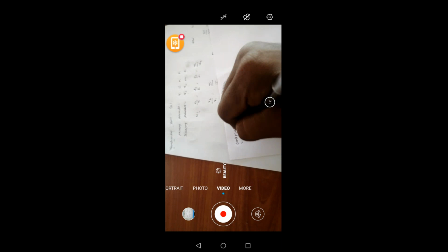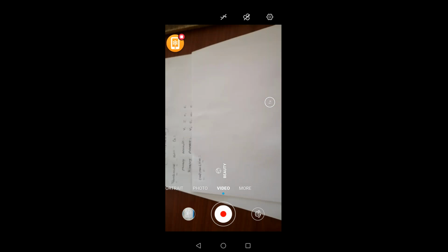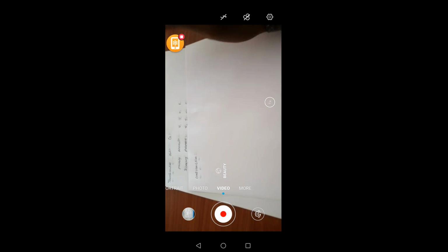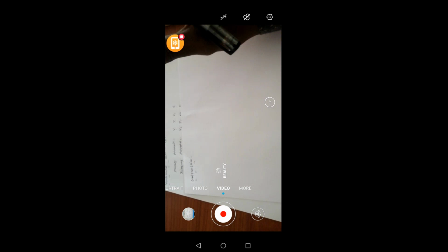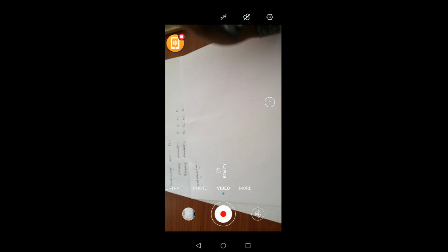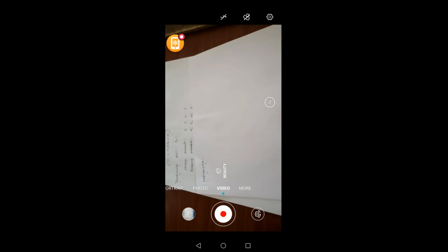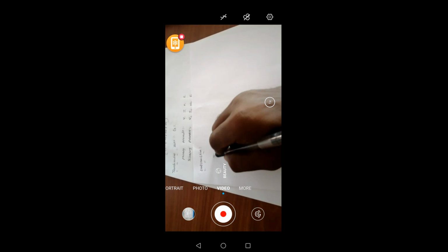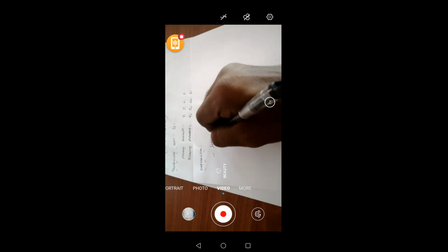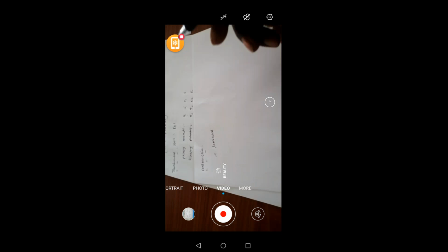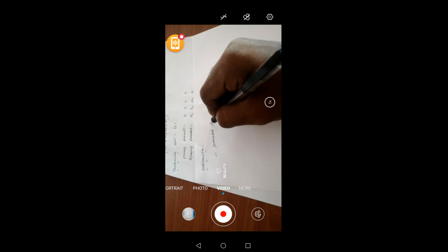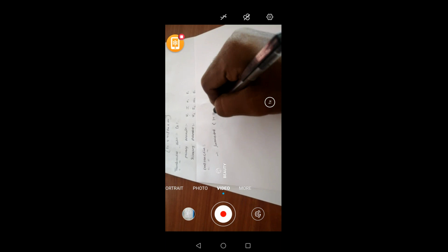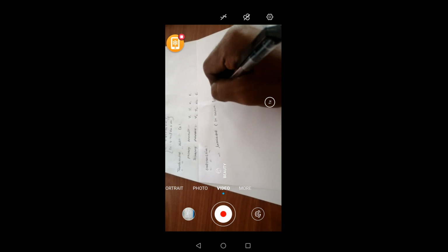So construction is the most important question. In a transformer unit, you may get the EMF equation or construction. So these two questions are important, and you can get any question from these two. Now let me see the construction. Before going to the construction, you have to write that the transformer has a laminated construction, and the laminated construction is used to reduce the eddy current losses. That is the purpose of lamination here.